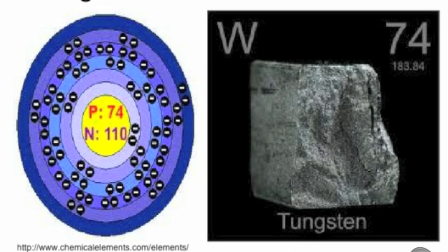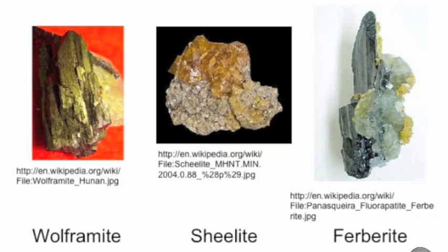When mixed with aqueous solutions, tungsten can form tungstic acid, also known as wolframic acid. Tungsten is normally extracted from 3 different ores: wolframite, scheelite, and ferberite. Once the ore is converted to tungsten-6 oxide, it can be heated with hydrogen or carbon to produce powdered tungsten. However, due to the melting point of tungsten, hydrogen reduction and pyrolytic decomposition are the best ways proven to extract tungsten.